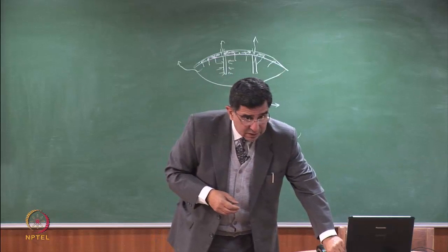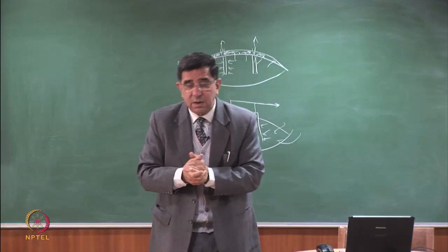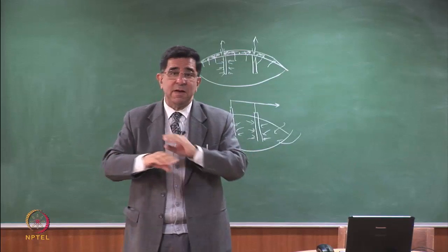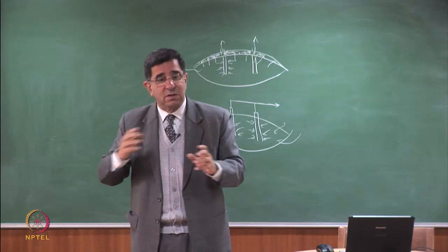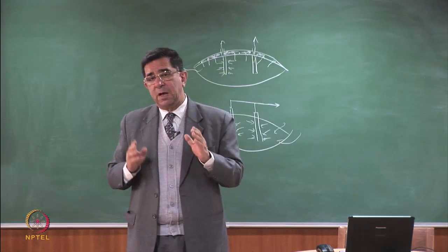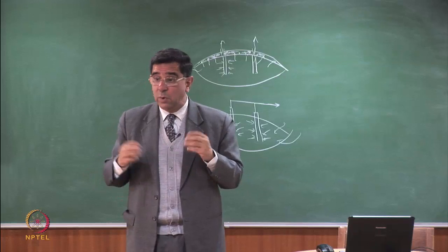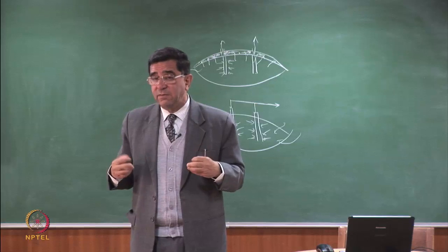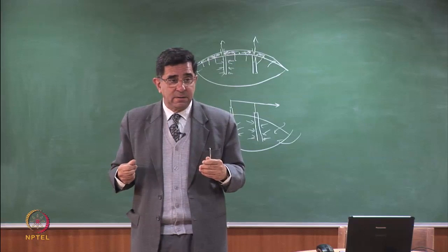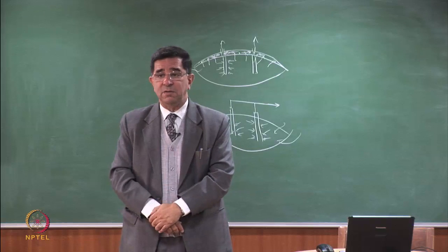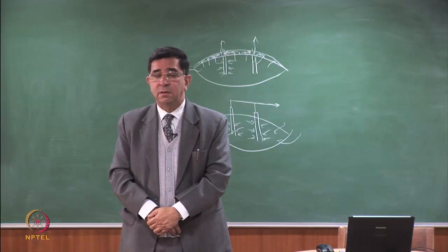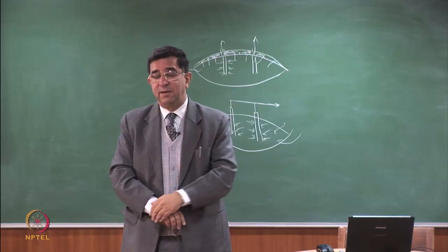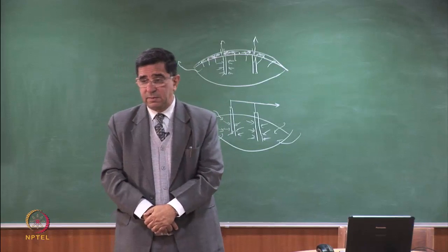As geotechnical engineers, it's not so much important for us to do the chemistry of what's going on inside, but be sure that the cap is well made, be sure that a gas collection layer doesn't mix with the layers around it. All these preferential paths, the drains, the horizontal drains, the wells, that is all that we have to design so that we can get a lot of gas and we can use it efficiently. So if you have any questions, I'll be happy to answer, or if you feel there's a better way of doing it, or a different way of doing it.